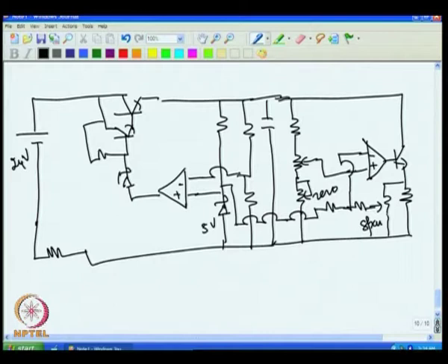One can adjust the 0 part to get 4 milliampere when the potentiometer is at one end, and when the potentiometer is at the other end, you can adjust the span part to get 20 milliampere. By repeatedly adjusting 0 and span a few times, one can make this a 4 to 20 milliampere current transmitter for the potentiometer.